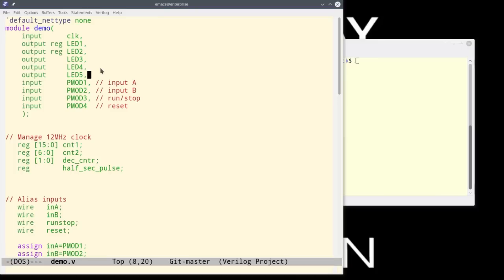If we just let the place and route tool randomly assign I/O pins to things, that's not going to work on our PC board. In particular, if I tried to drive an output on a pin that was already connected, say, directly to ground or directly to power, I could potentially short something out and burn up my FPGA. For a $22 FPGA board, that isn't the worst thing in the world, but a lot of FPGAs are a lot more expensive than $22. So you generally don't want to do that.